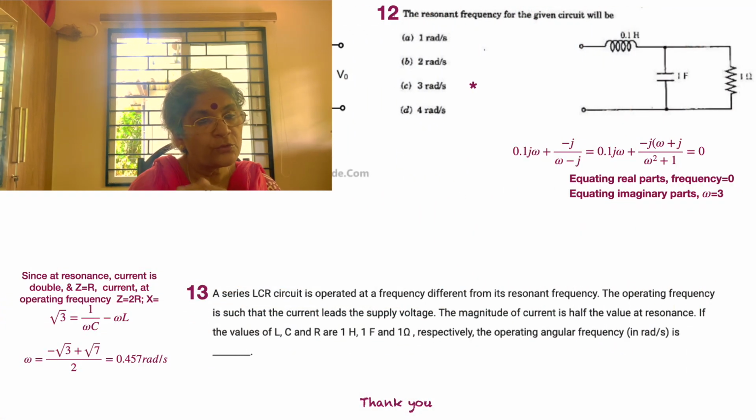So R is equal to 1, so the total impedance is equal to 2. So how do you get the reactance X? By square root of Z square minus 1, where 1 happened to be the square value of resistance of 1 ohm. So that's equal to root 3. So now X value is equal to root 3.